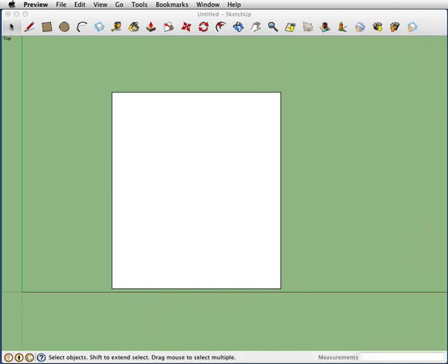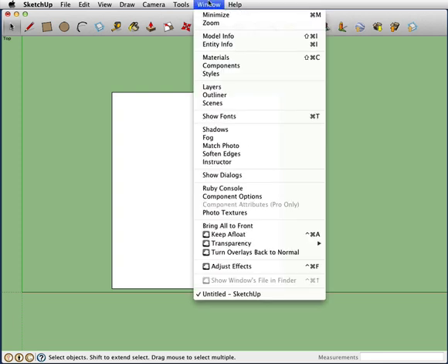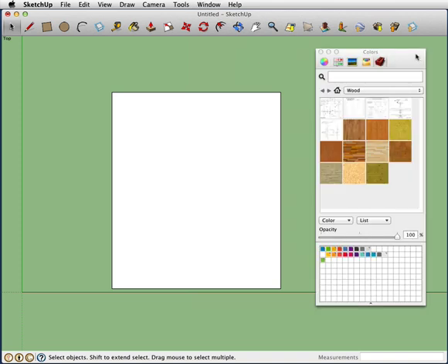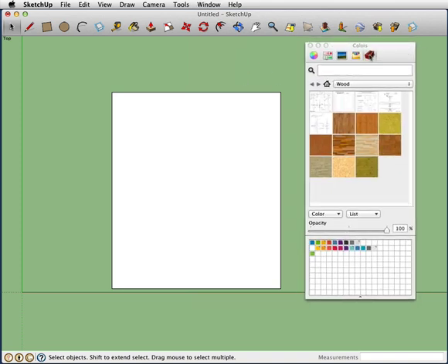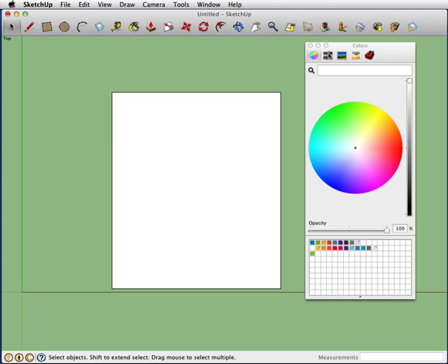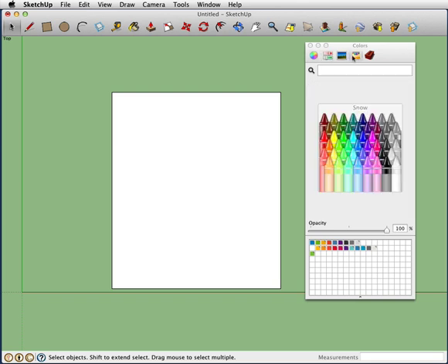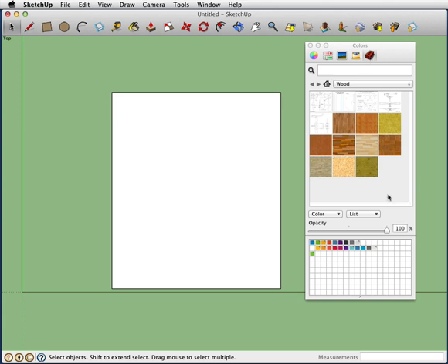So how do we get that into SketchUp, into something that we can use? Well, we're going to do that with a texture. And to do that, we're going to have to open up a different window that we haven't used before, and it's going to be the Materials window. When you open the Materials window, the icon that you want to select across the top, which is sort of the category, these are just colors, is the one that looks like a brick, and it's the texture palette. And what we're going to do is we're going to create a new texture down here in the empty space.